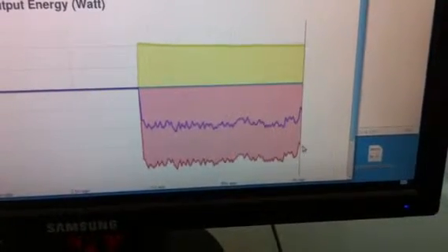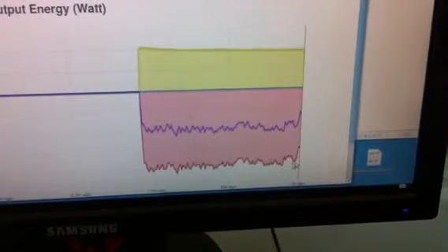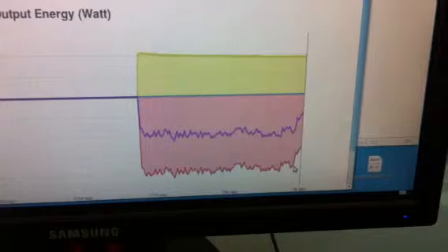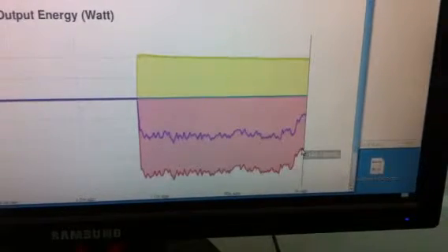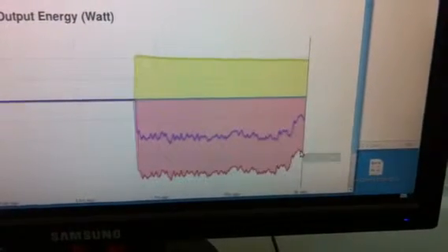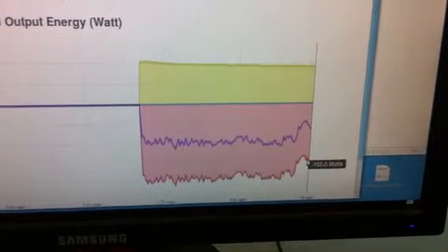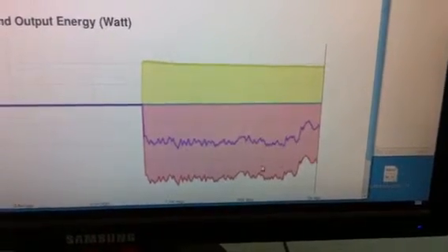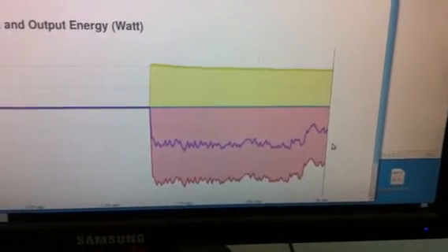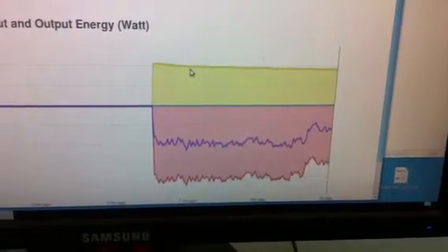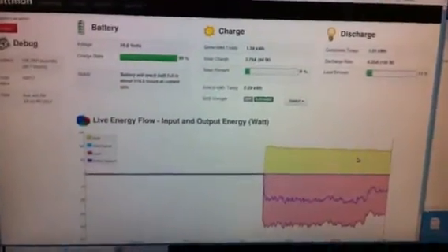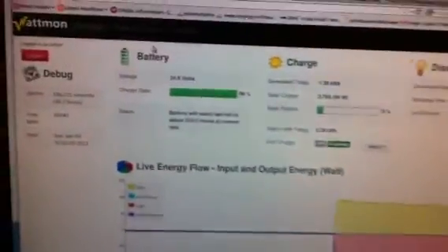Right. Now you can see that the load has gone down from just over 195 watts to about 143 watts. So I can immediately see that the fan has been using nearly 50 watts of energy. I can do this for any device in the house and get a quick update and understand what's happening, where my energy is going.